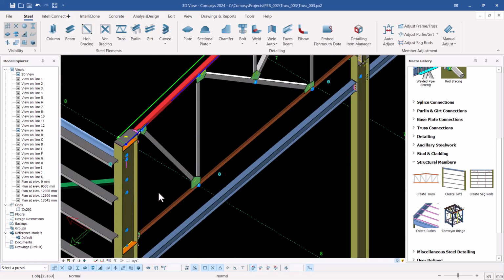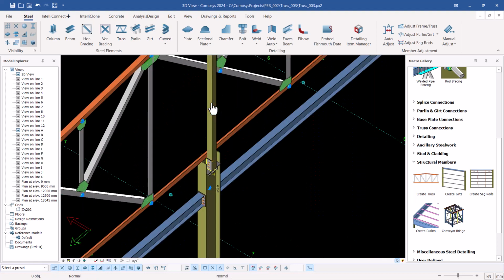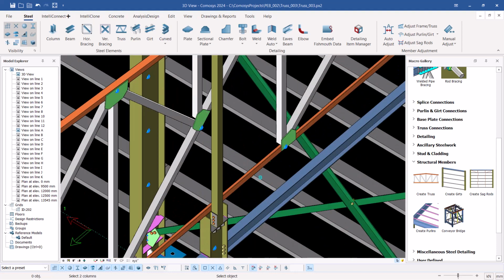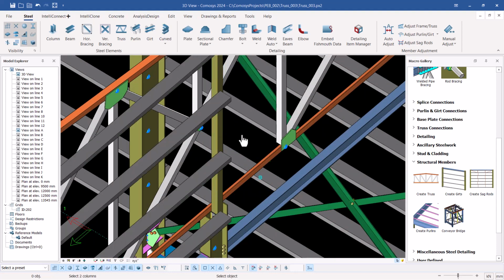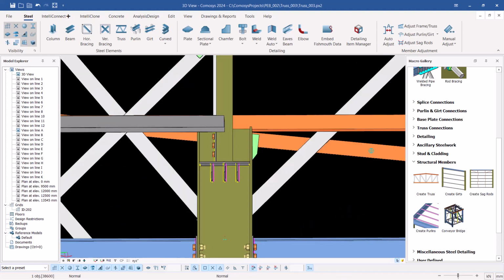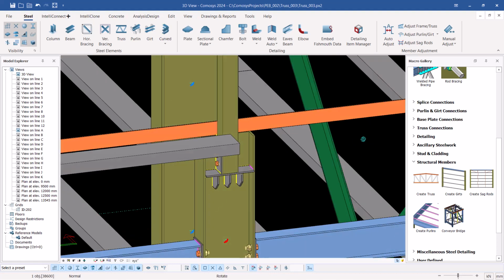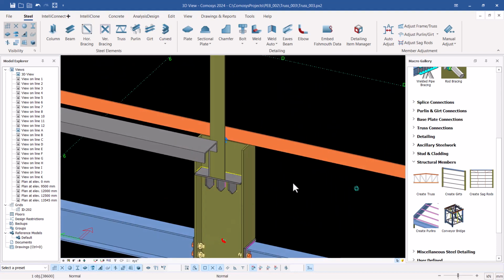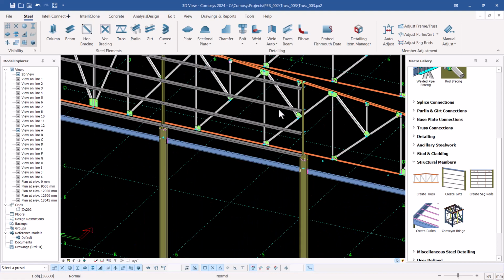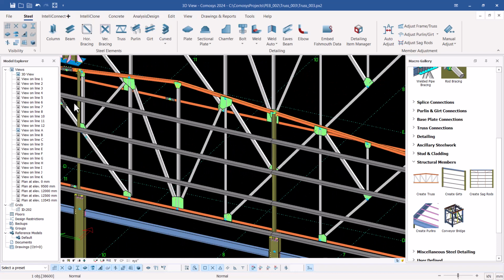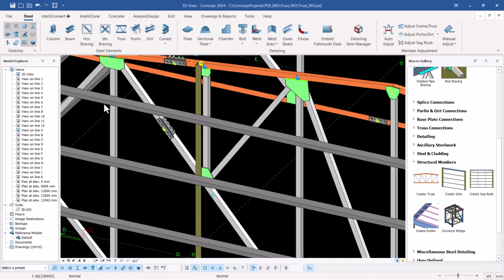So what I'm going to do, I'm going to pick on the guards and pick this member as a column and move all the way to the last one, which is here. So once I've done so, I'll be able to create guards there. And another thing, as usual, you'll be able to see there's a slight off placement of the guards. So if any needs adjustments, you just click and press letter M and enter, and you'll be able to adjust that. So you can see here we have a joint, and let's move it all the way to that spot. And here also we have a joint.